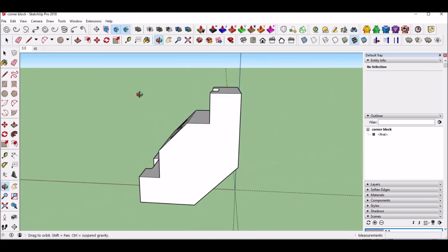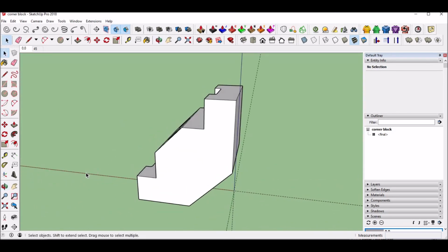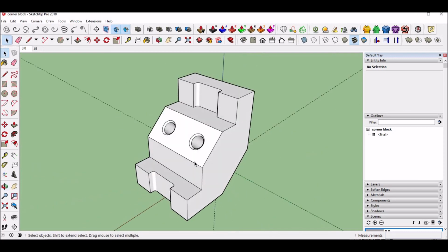Okay, so anyways, some tips and tricks in there. Remember to rotate the axes, to have the blue axis perpendicular to this face to make those chamfers, and it'll be good to go. So thank you for watching this one. In the last video, part 5, we're going to talk about rendering. So let's go ahead and stop here, and then we'll begin the next one shortly.